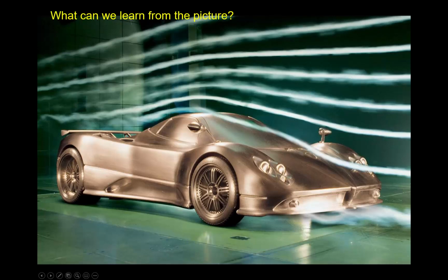Like if you think about it, the fan is blowing the wind through the entire wind tunnel, but now here you have an obstacle in the path of some of the wind. And so the wind that's coming up over the vehicle has to speed up, because it has a smaller cross-sectional area for that same mass of air to pass through. Whereas it has a relatively large cross-sectional area here before it encounters the vehicle, when it gets to the passenger compartment, there's a smaller cross-sectional area, so the velocity is going up. So it makes sense conceptually why the velocity would be going up, but then we also have this visual representation.